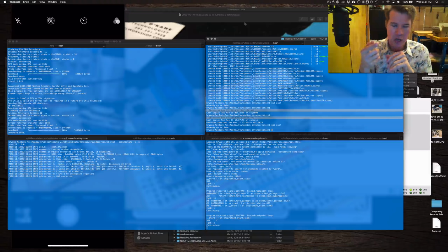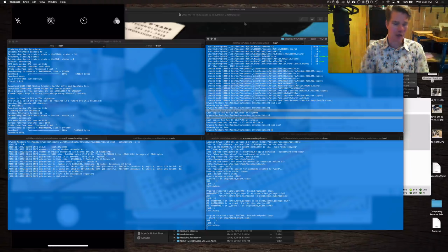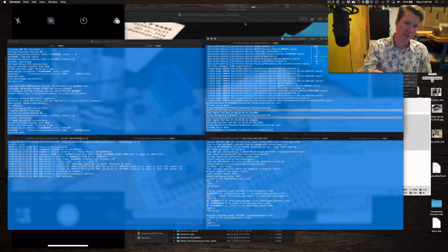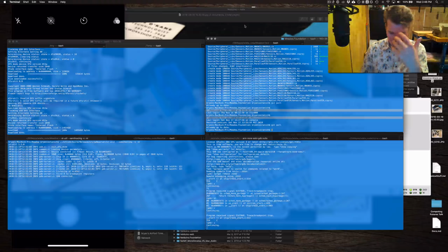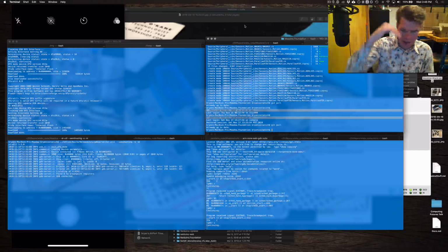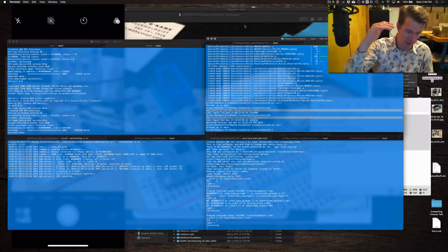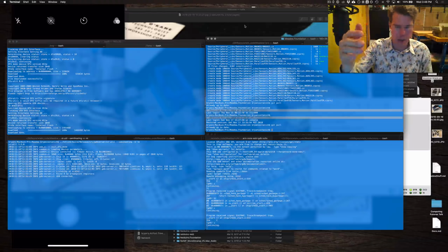The first way is to put it into bootloader mode by holding down the boot button and plugging the USB in, and then we can shove our package over onto the device's flash. That is a very reliable way to get the Meadow package, which is the operating system and the APIs, and then your app.